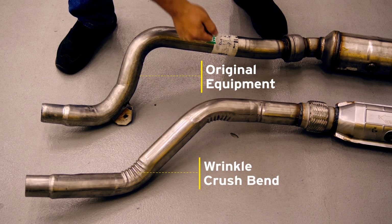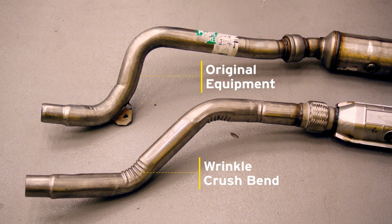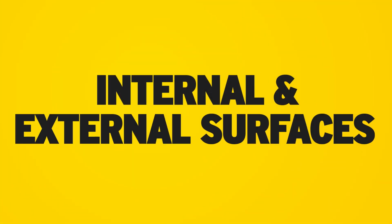The tube deformation of this cost-saving measure creates an impingement that reduces exhaust flow as well as compromises geometry compared to the OEM converter. The subsequent decrease in flow can cause a reduction in fuel economy and a loss of engine performance. Mandrel bent tubing maintains smooth internal and external surfaces.